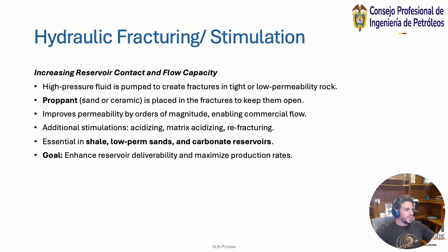Hydraulic fracturing. So here you're increasing the reservoir contact and flow capacity. What that means is, so let's talk about what hydraulic fracturing is before we go through these points. Hydraulic fracturing is that you take these 200-ton trucks, right? And you should see a picture of it, but these 200-ton trucks are all pointing to the same thing, and you push at a very high pressure this amount of fluid. And usually in a frac job, you have this thing called pad, you have this fluid, and you have some sort of proppant, right?